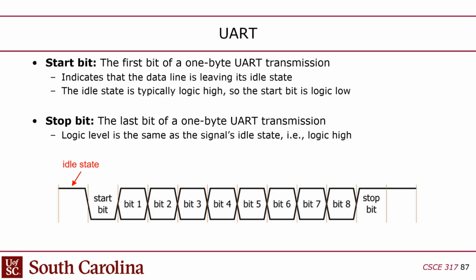That was a decision. But the start bit is when there's 1 bit period that's 0. And then likewise, the stop bit is 1 bit period where it's 1. The reason for that is that if your start bit is a 0 and your stop bit is a 1, that guarantees that you're going to have, well, I shouldn't say at least, because it's not like there's a clock. This is the data line.